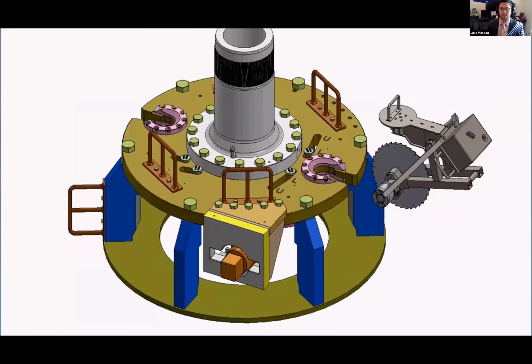All right, guys, now I'm going to talk to you about some of the design analysis that got us to where we are now. First, we're going to talk about the variables that we use in the hydraulic calculations. Q is flow rate, D is the inner diameter of the hose, DT is the displacement rate, P1 is the inlet pressure read by the pressure gauge. The first calculation we did was a fluid velocity calculation, which we found to be 16.43 feet per second, which was used to size all the hoses in the hydraulic system.